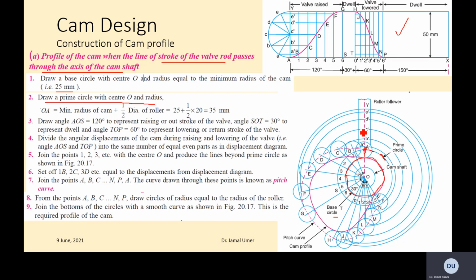So of course you can imagine when it moves over here. So when it's moving, the cam actually is a little farther. How farther? The half of the diameter of the roller. So this trace point A is farther from the cam profile. If it's a knife edge, this is exactly sitting on the cam profile. But now because of the presence of the roller, this will stay away throughout the profile. And how far will it stay away? This will stay away the radius of the roller.